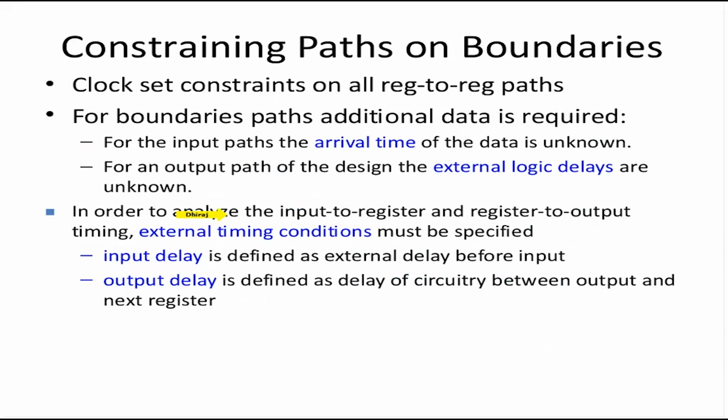Input delay is defined as the external delay before the input. Output delay is defined as the delay of the circuitry between the output and the next register. Please note, both input and output delay are for the external world. They are not for your design, because input delay and output delay will be estimated values for the external interface. Let's see how these values are used to constrain these paths.